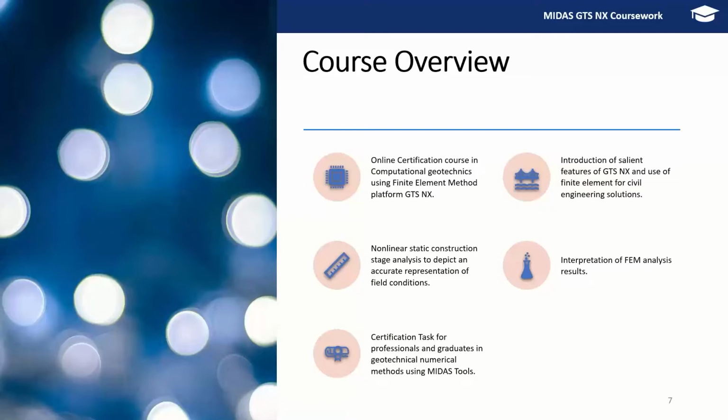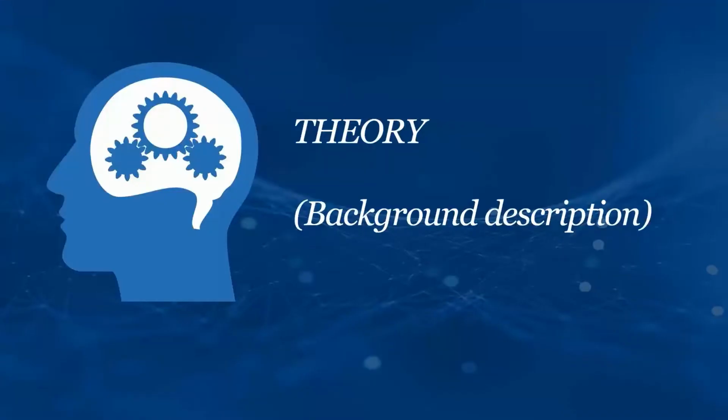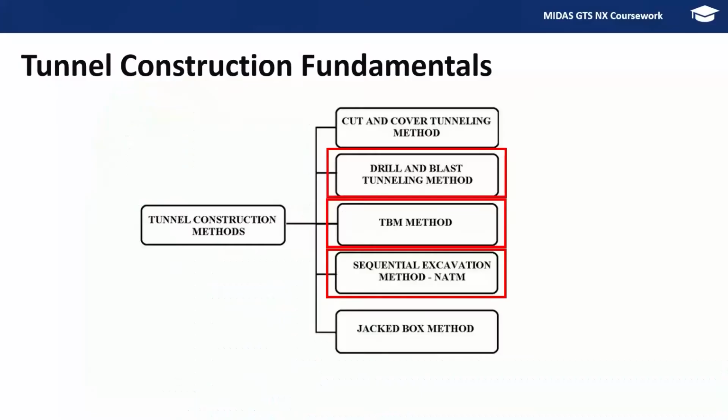And with that being clear, we'll start with the background description of today's main agenda, that is the tunnel construction and the seepage into the tunnel construction boundaries. So in terms of the various tunnel construction fundamentals or the methods, the most predominant methods are the cut and cover tunneling method, the DNB or the drill and blast method, the TBM method, and the sequential excavation NATM method, and the jacked box method.